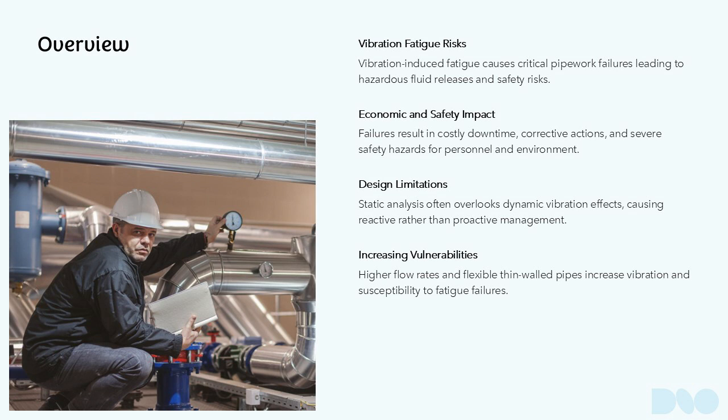Increased flow rates due to debottlenecking and relaxation of erosion velocity limits have led to higher fluid velocities, which in turn generate greater turbulent energy within process systems. Furthermore, the adoption of thin-walled piping materials, such as duplex stainless steel alloys, has made systems more flexible and susceptible to stress concentrations, particularly at small bore connections.